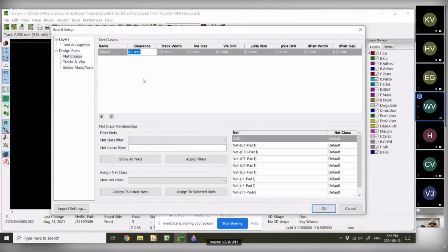So normally the clearance between lines is 0.2 millimeters. If you want something wider, you can change it. Or if you're like me, making a PCB at home and I don't trust my ability to produce the separation by acid, I might want to make them farther apart and maybe even a bit thicker, just to be sure I get something.